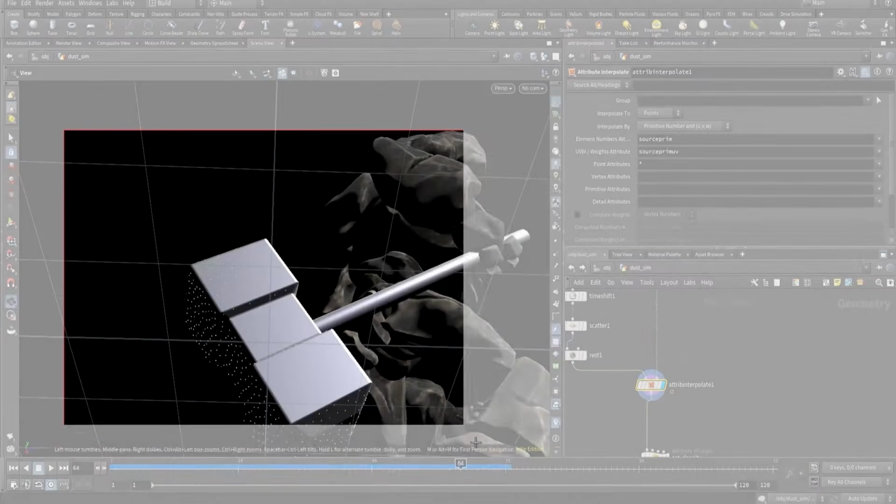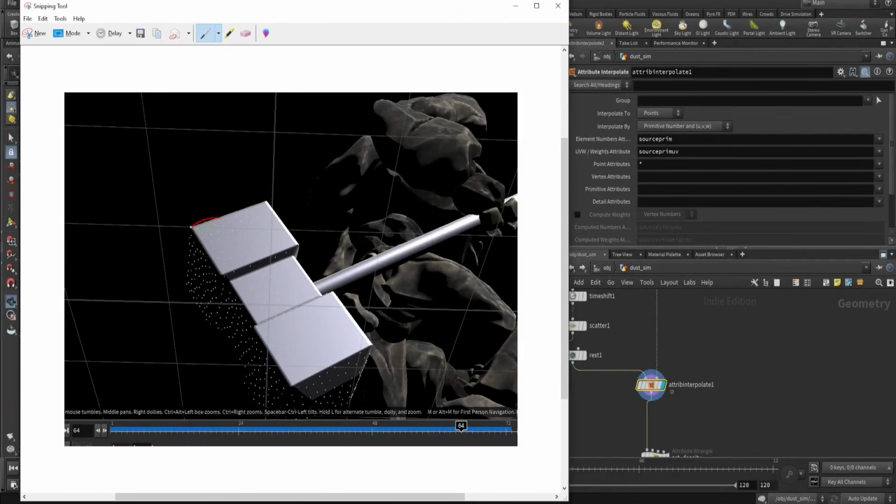Let me just take a screenshot of this. So this is the current frame and the previous frame is this. Here we don't have data in this area. What substeps will do, if you use two substeps, it will just add one more data in here. And if we use three substeps, then it will add three data in here. But substeps will also increase the simulation time 3 times. So that's not the solution for this kind of issue. What we can do is fill the gap at the source level only. Let me show you how we can do that.